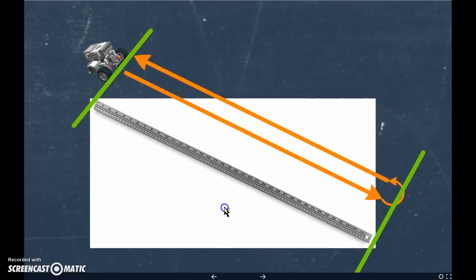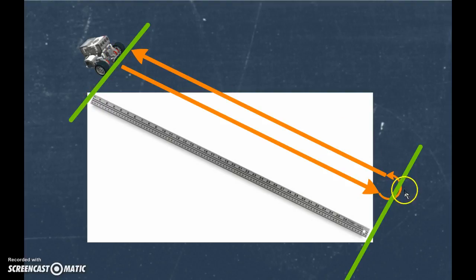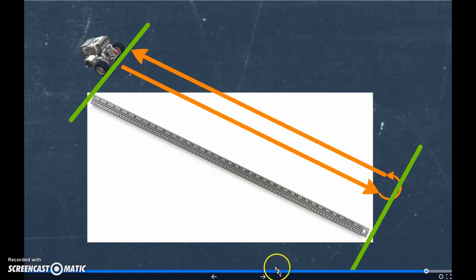Then you want to instruct them on how to set up their test. They should line up the wheels behind 0 on their meter stick and run their tests and go through the engineering design process until they can make this thing do the whole mission. And they have to make adjustments. If it goes too far, they need to choose less seconds on the first and third blocks. If it goes too far this way, same thing. They may need to adjust the turn sometimes. Every robot's different for some reason.